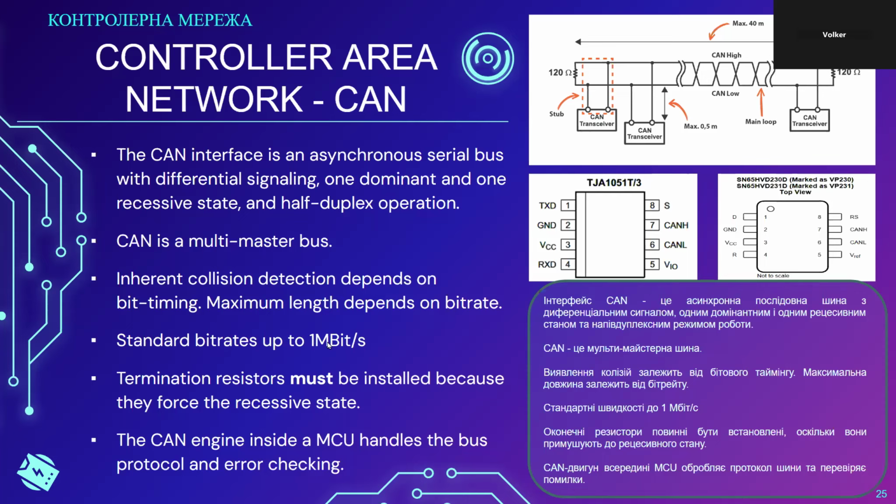So you don't want to introduce large jumps in this 3.3 reference voltage because the CAN controller is suddenly demanding 50 milliamps or possibly more, maybe 70 milliamps. So you want to decouple the 3.3 volt power from the CAN controller. And that's where having a separate VIO input can be useful.